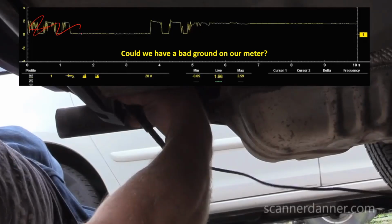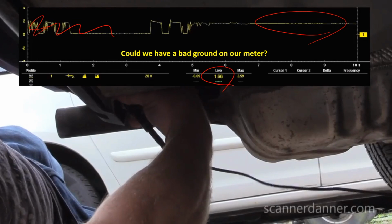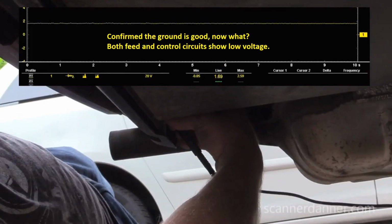I'm moving the ground around, and this is a steady signal, and I'm reading 1.66 volts. Originally I was at 1.57. So did I improve my ground a little bit by now seeing 1.66? I did. And I think there's 1.69. Confirmed, ground is good. Now what? That's my question. My ground's good, that would be my one variable. Where are we going now?